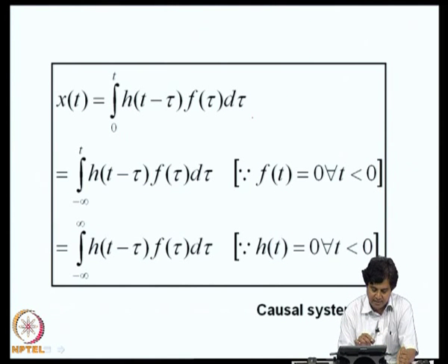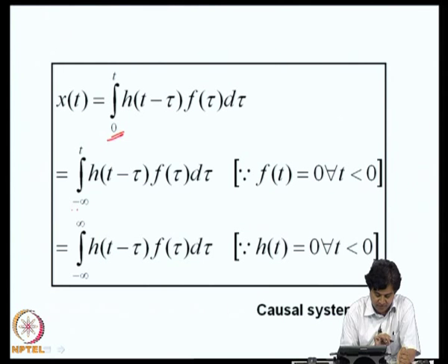So, what we will do now is reconsider this Duhamel's integral. This is the response of the system when it starts from rest under the action of load f of t. Now, we would like to rewrite it in a slightly different form. The first thing is I want to write this lower limit as minus infinity. This is admissible because we define the force to act on the system from t equal to 0, and when t is negative we take f of t to be 0. If this is acceptable, I can as well write 0 as minus infinity.